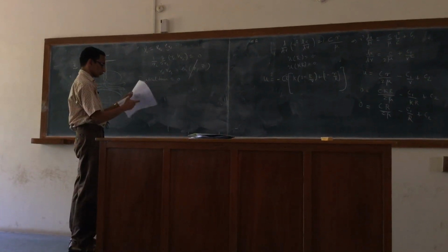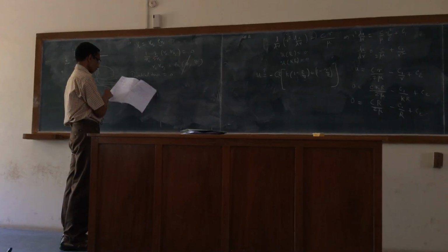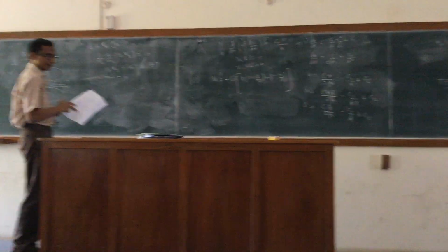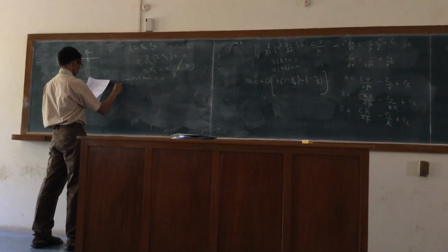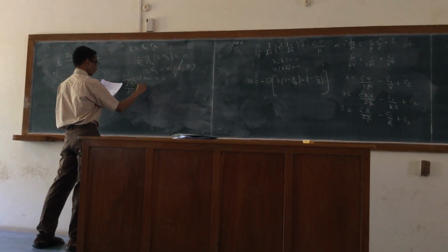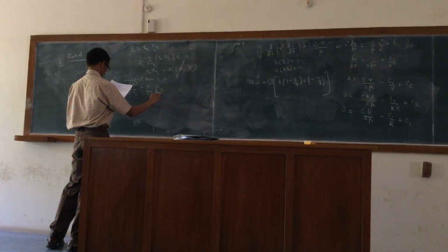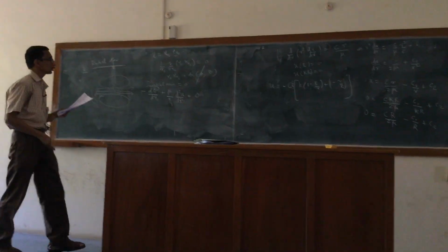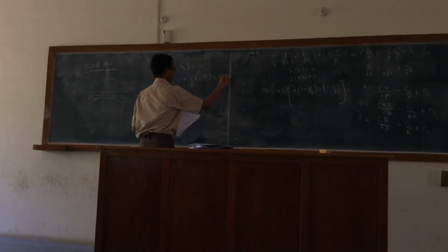And so if you work through the equations, then you will get the answer that is given, right? What you should get is minus dP by dr plus the viscous term equal to 0. So this is what I call u of z.